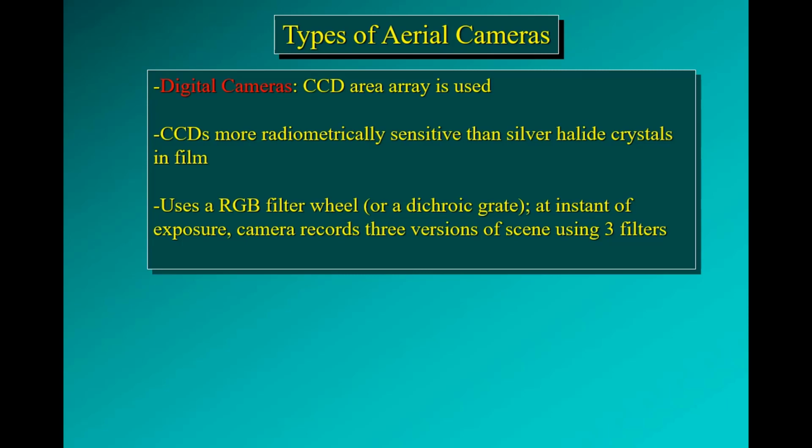And this could translate potentially into differences on the order of hundreds of feet on the ground between the various images. So if this is the case, then the individual image bands are not going to be automatically geometrically registered with one another. And if that is the case, we must use digital image processing techniques in order to register one of those image bands to another.